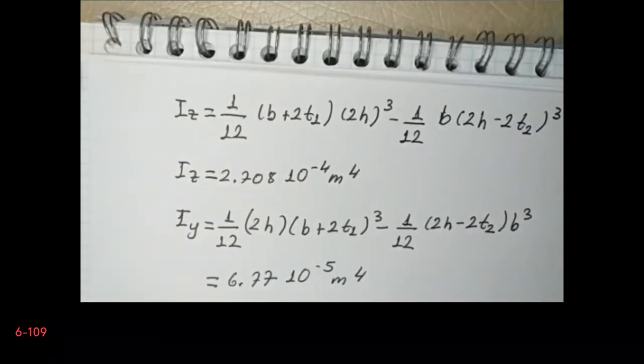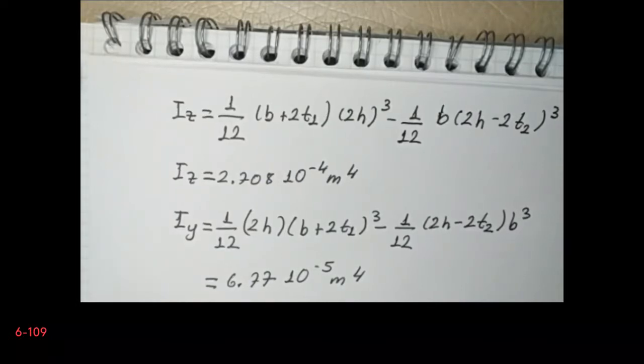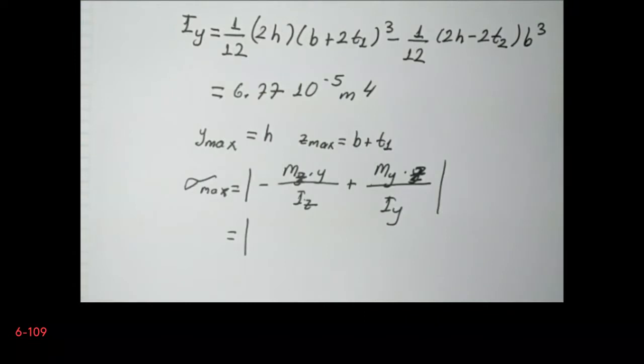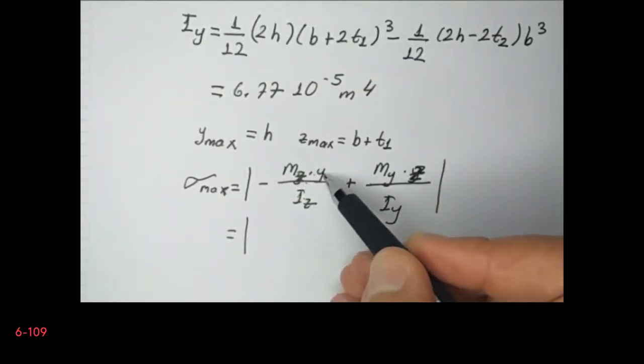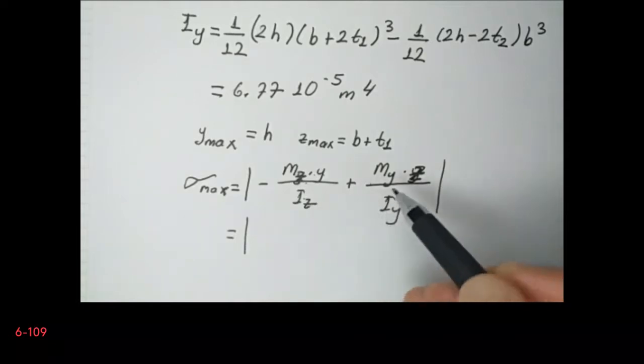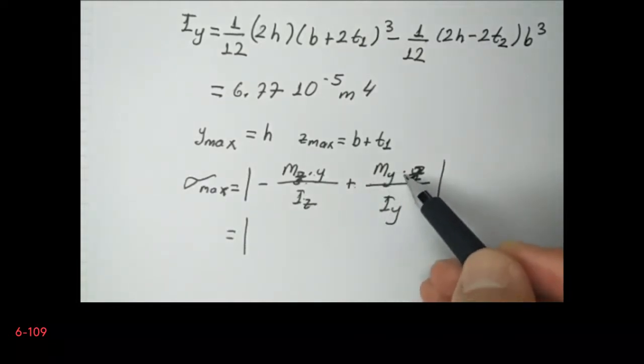So this is my stress: Mz multiplied by y divided by Iz plus My multiplied by z divided by Iy.